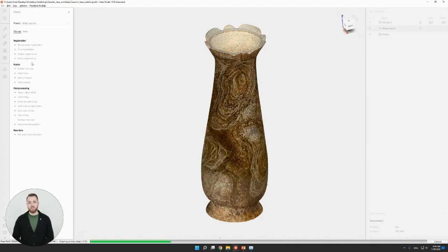Camera field of view, this is the third setting. And this parameter you will need to change very rarely. Artec Studio determines this value automatically using photo metadata. So it checks your pictures and gets this number from there. But if it cannot be done for whatever reason automatically, you can specify it manually, right?